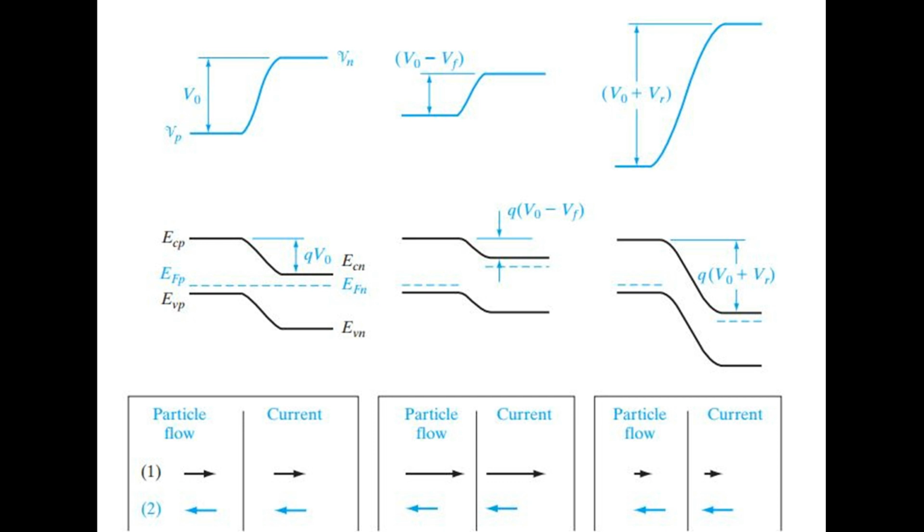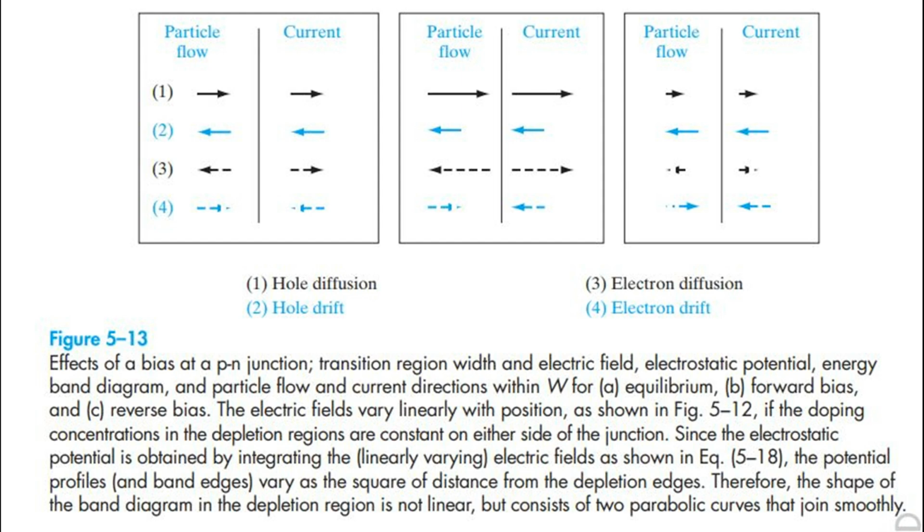The diffusion current is composed of majority carrier electrons on the N side surmounting the potential energy barrier to diffuse to the P side, and holes surmounting their barrier from P to N. There is a distribution of energies for electrons in the N-side conduction band, Fig 3.16, and some electrons in the high-energy tail of the distribution have enough energy to diffuse from N to P at equilibrium in spite of the barrier.